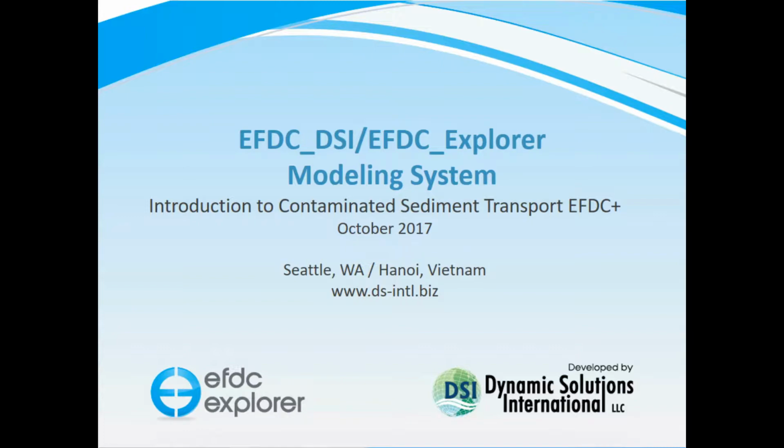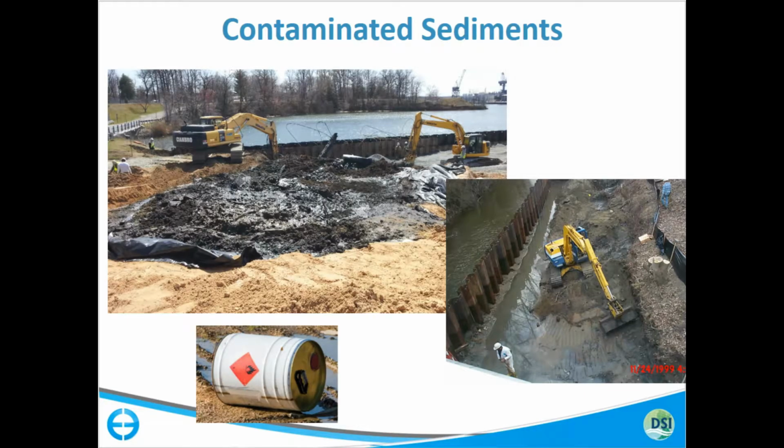That's the reason why you pretty much have to have the sediment transport model working before you can turn on the toxics model. And EE prevents you from turning on the toxics model right now unless you first have the sediment transport module turned on. So when we're talking about toxics transport in EFDC, anybody, not just us, it'll be always associated with a contaminated sediment issue.